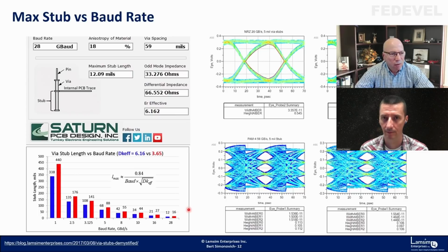But if that via is designed properly, it should go through. It will have an effect. There will be some loss in the via, but not huge, right? So the best is just to route on the layer where the components are. No vias. Well, that would be in a perfect world, but we're not there.